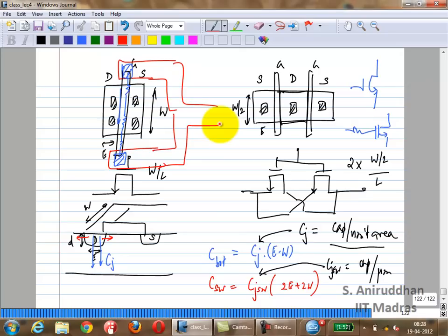right? Doing dual gate contacts is usually considered a good practice, unless you run out of metal layers and it's not needed. In some cases it may be needed, some cases it may not be needed. You will have to make the decision. In most cases, it is very useful. Okay. What else? Yes.